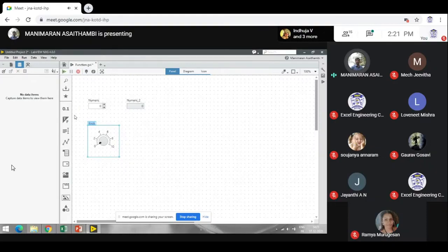Do you see this icon has an error? So I cannot run my program. This icon is throwing an error. When I double click this icon, it will tell me this error belongs to here, this error belongs to here, so it tells me where exactly the error is. I take a wire and connect here. This needs 2 inputs. I connect over here. Now I go to my front panel.